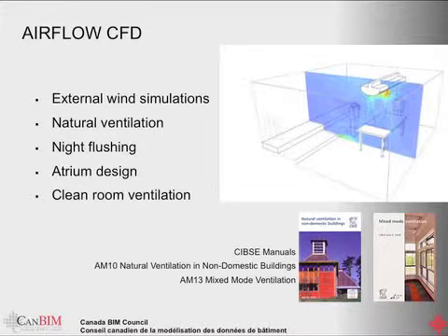And now airflow. So again, airflow, not very common up here, but we can start to bring all this data in about natural ventilation. Night flushing is getting very common. Atrium design, optimizing atrium designs, because sometimes we're just blasting a bunch of air in atriums, or we don't have to. We can, and what the purpose of natural ventilation ultimately is just to reduce summertime cooling peak load. That's ultimately what it is.